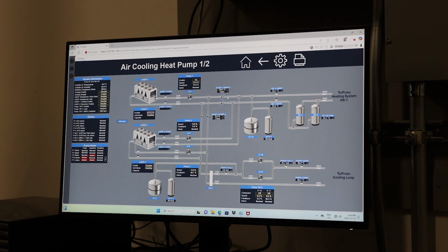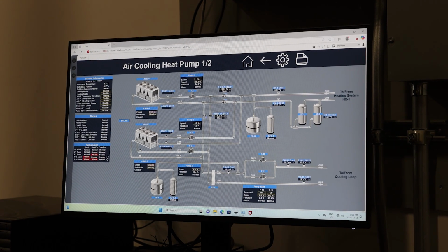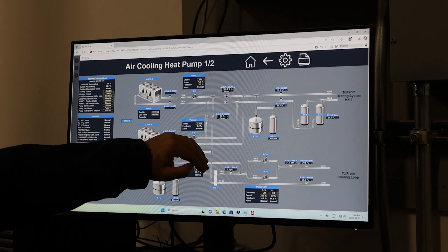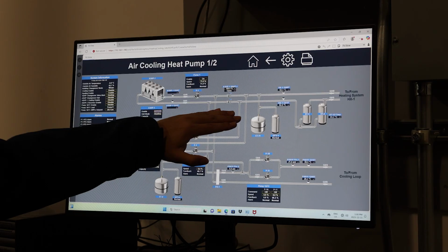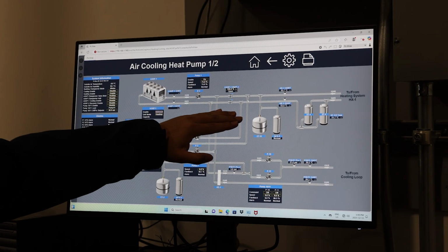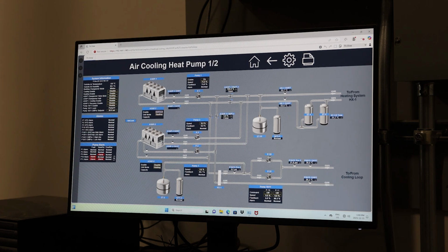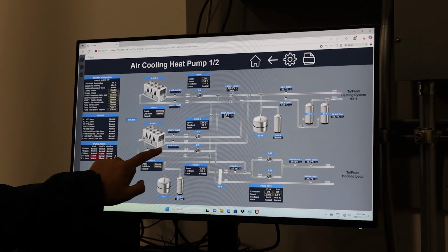So the flow from the pump goes to air source heat pump 1. It doesn't go down because below is the cooling side. So the cooling valve is just closed, just capped. Flow just goes through here, and here we have a T. This T comes from pump 2, which is the heating side of air source heat pump 2.